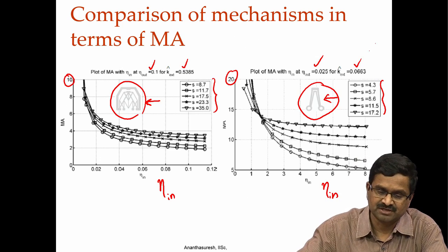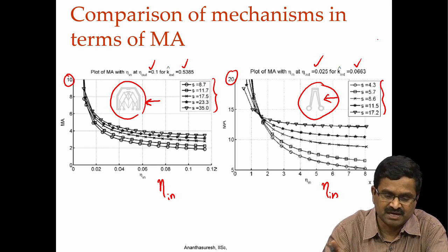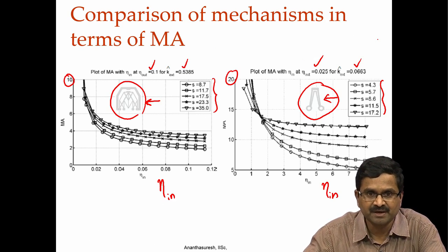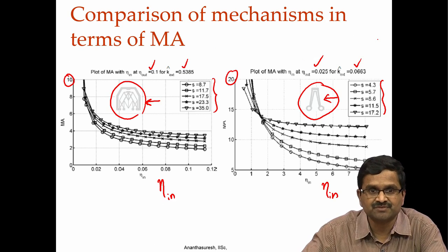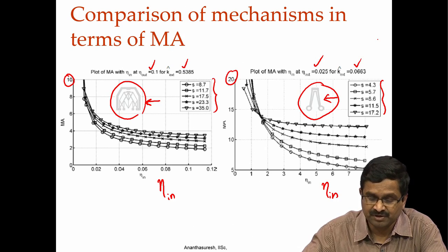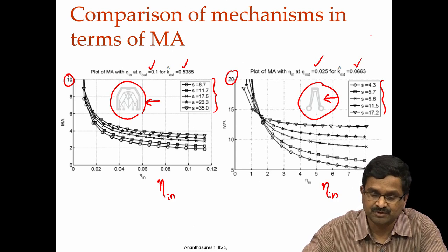So, that is how these charts can be used, and you can compare different compliant mechanisms as it is shown here. So, we have a database of 85 mechanisms. If we have these charts for all of them, these are kineto-elastic maps here. So, we can also wonder about how the mechanical advantage changes, which one to choose.